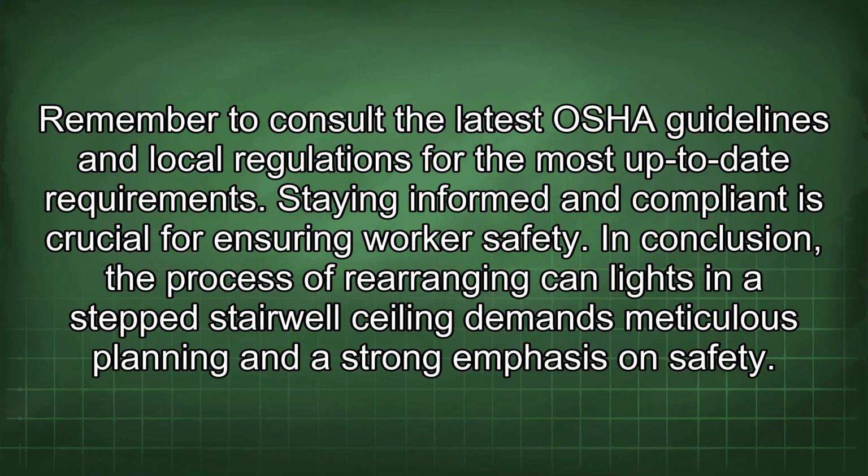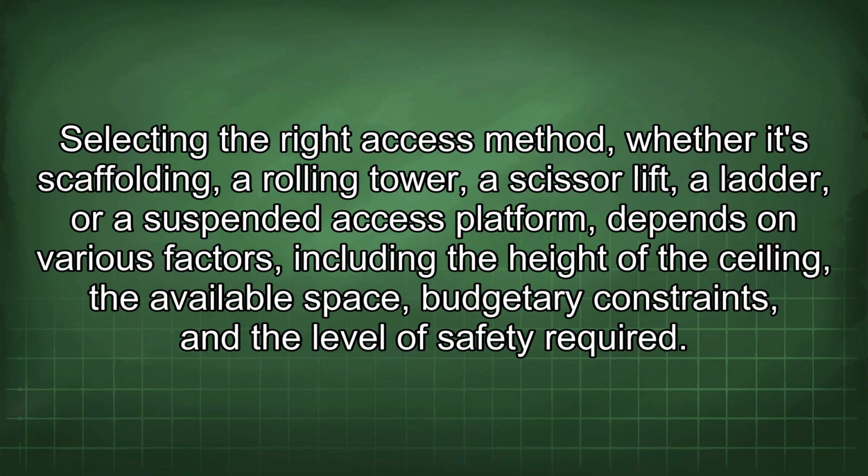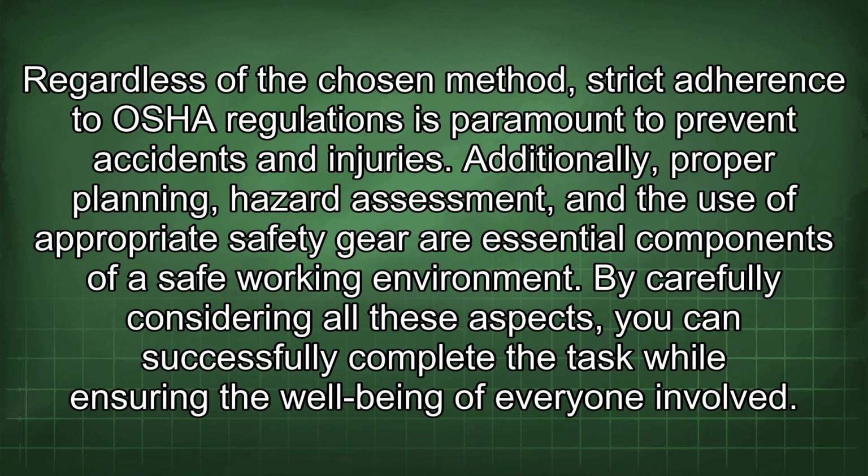In conclusion, the process of rearranging lights in a stepped stairwell ceiling demands meticulous planning and a strong emphasis on safety. Selecting the right access method, whether it's scaffolding, a rolling tower, a scissor lift, a ladder, or a suspended access platform, depends on various factors, including the height of the ceiling, the available space, budgetary constraints, and the level of safety required. Regardless of the chosen method, strict adherence to OSHA regulations is paramount to prevent accidents and injuries.